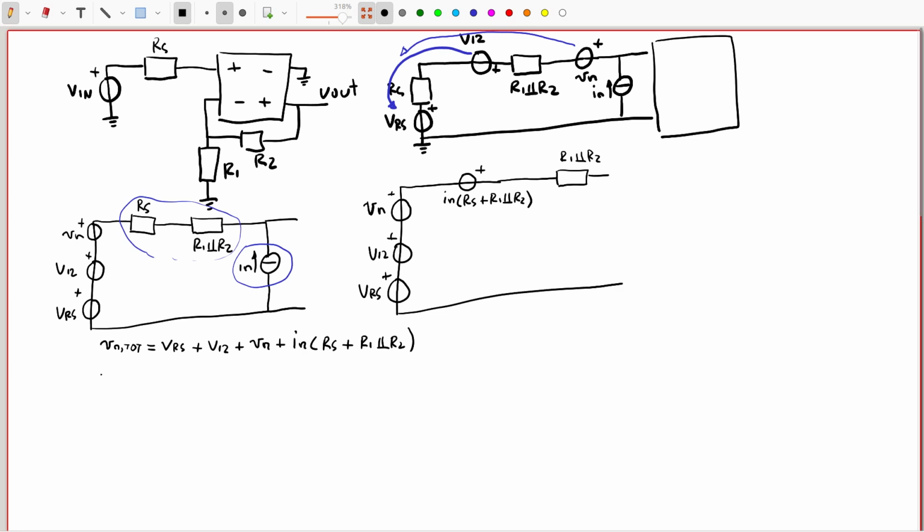And we continue Vn tot. We remember that if we assume that we are going to have a single input common source transistor, then we have that En is going to be equal to Vn G omega C, the total capacitance at the input, under the assumption that we are going to use a single input transistor like this common source amplifier.